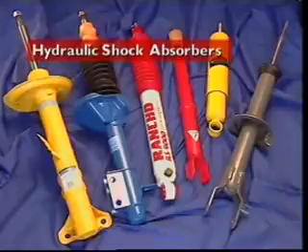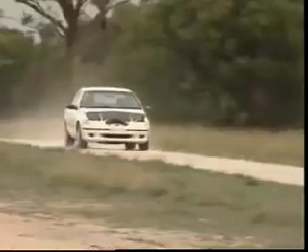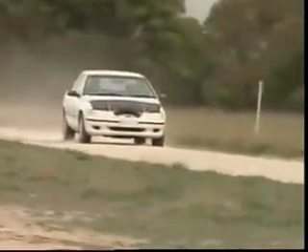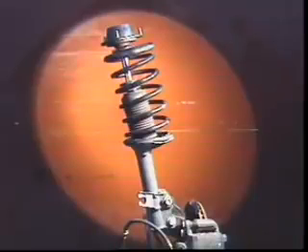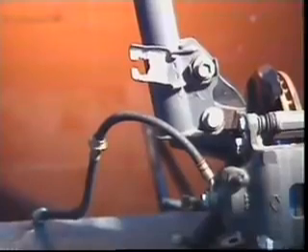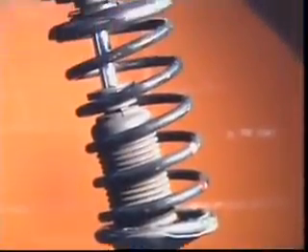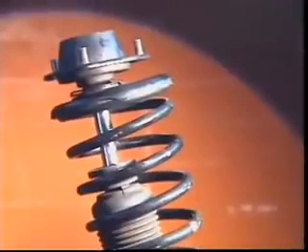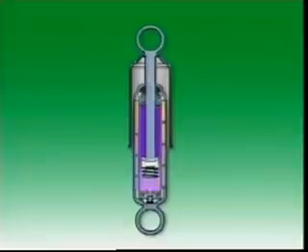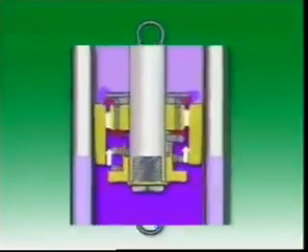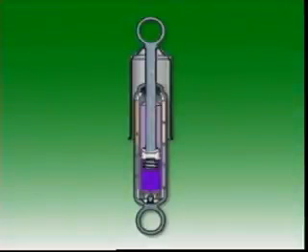This section examines hydraulic shock absorbers. The most widely used hydraulic shock absorber is the direct-acting telescopic type. It can be fitted as a self-contained unit or combined with a suspension strut. The strut type uses the same principle of operation but is considerably larger. The hydraulic shock absorber provides its dampening action by transferring oil under pressure through valves which restrict the oil flow.